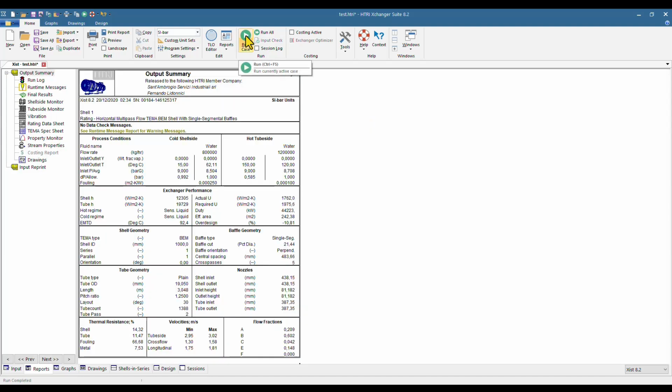Now we have reduced a lot of surface, of course, by cutting the tube length to 50% of the original tube length. So we are under surface of about 10–11%. We are within the limits of the shell side pressure drop, but we have a space on the tube side pressure drop. So the idea could be to either adjust the number of passes.